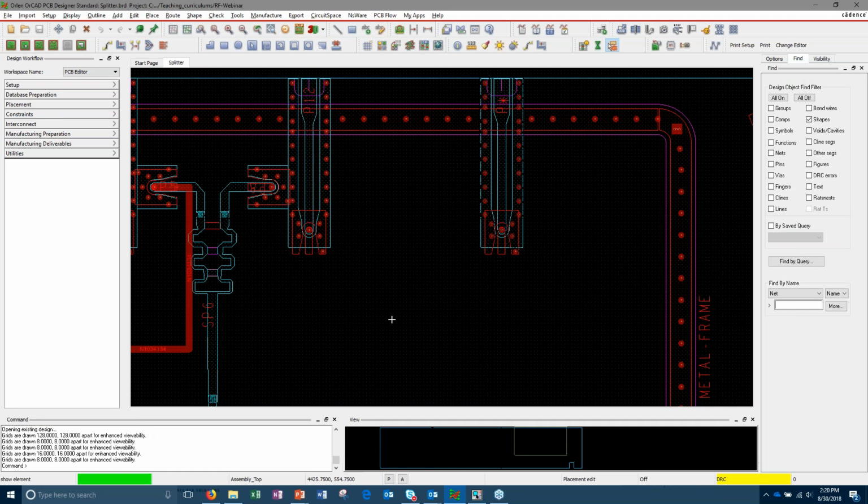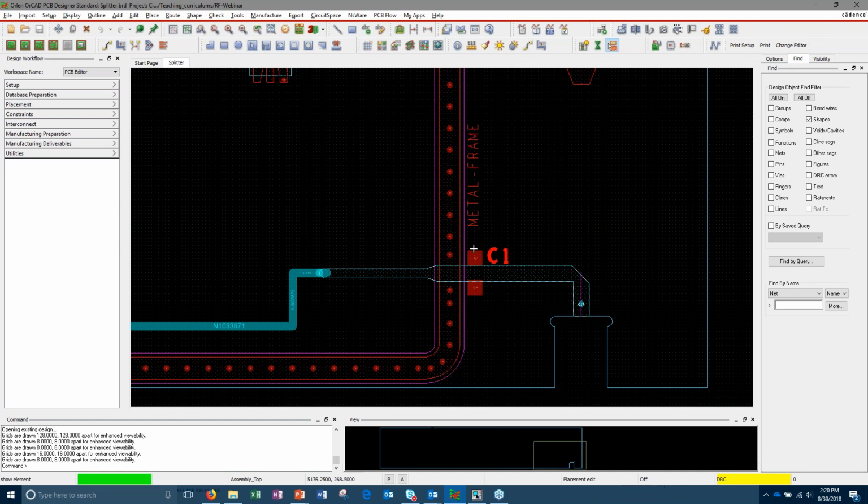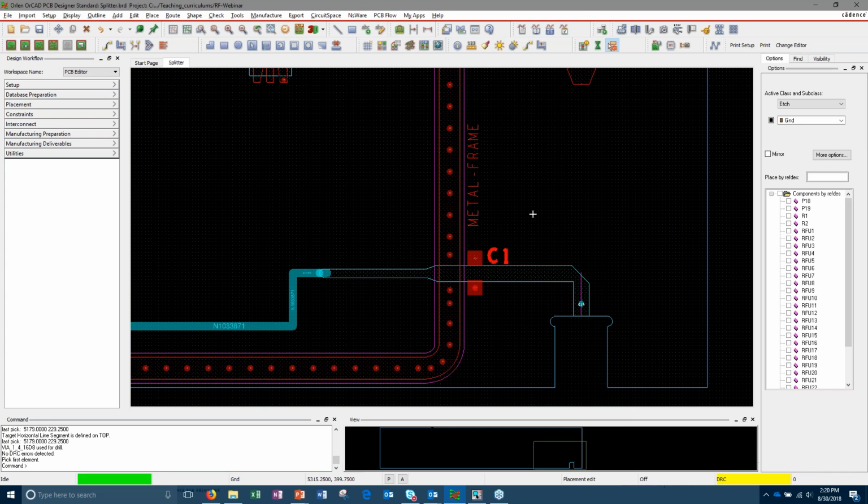So at that point here, I want to go in, we talked about putting a via in pad. So if I'm going in there and I want to do my connection, I can go into here and click on this, and I can do a right mouse button, just say add via. Our software is going to allow you to add that via right into the pad. That's the best connection that you could possibly make. RF boards are expensive, so that cost of plugging that via is not that big of a deal in the overall cost, but performance is more important at times than cost. So the software will allow you to put that via in pad.